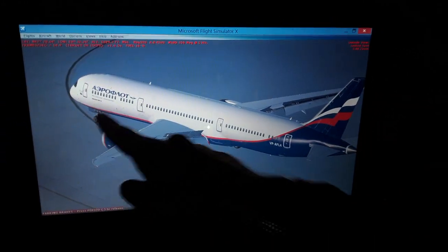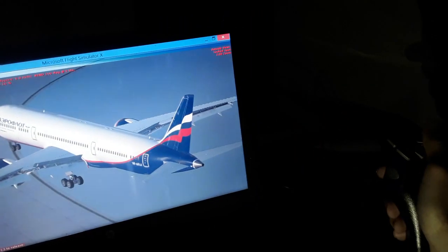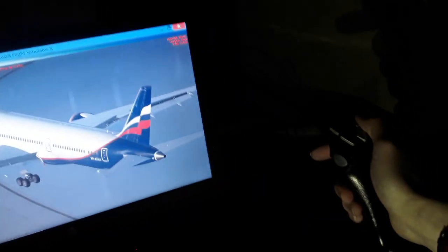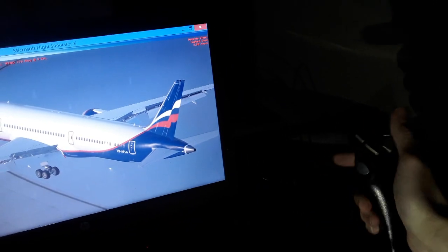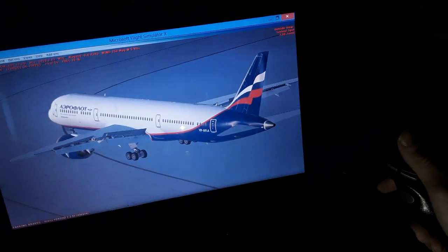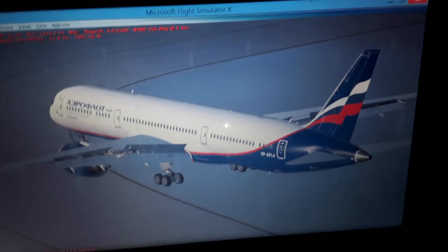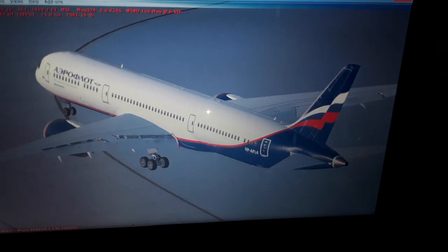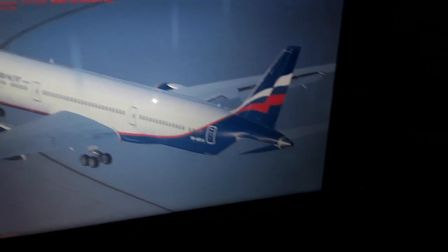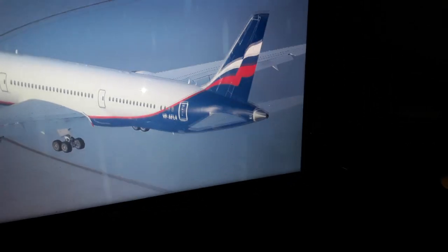As we increase the airspeed for takeoff, it decreases to like 7.6 degrees left and right, and we have more aerodynamically effective rudder. So you can see the rudder, the elevator for climb and descent, turns left and turns right, ailerons and spoilers. So you see all flight controls movement.